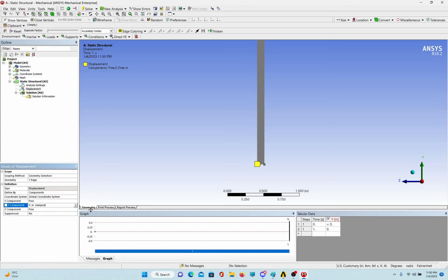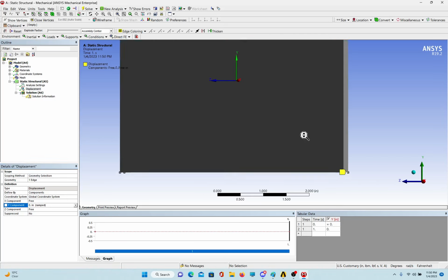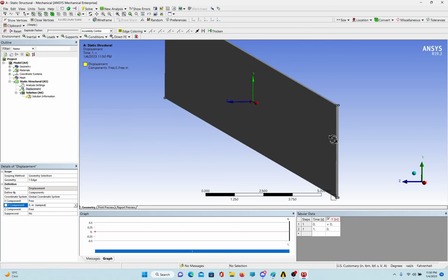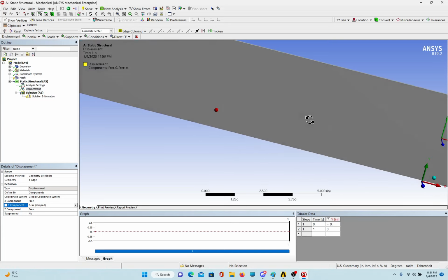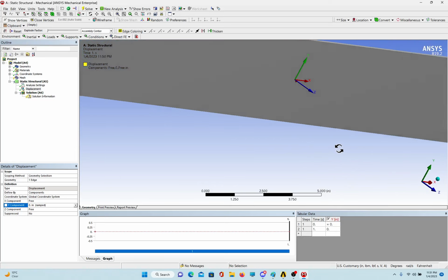As we have a simply supported beam, it will restrict our movement in the y direction. So in order to model it, I have restricted the displacement in the y direction, and if we have to model it in 2D, remember that also, because we have to incorporate that in our simulation as well. So as we have simple supports on both sides, going on to the other side, you can see that this is the negative axis. Click here.